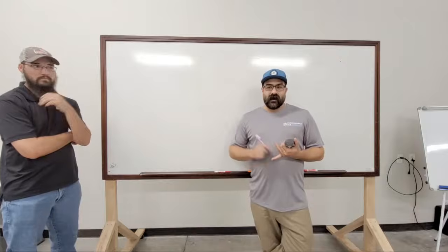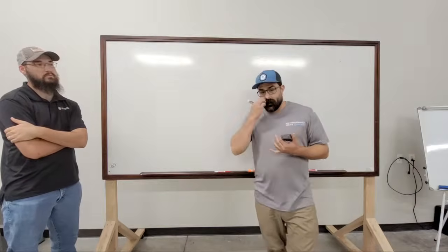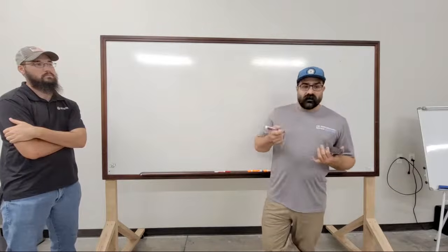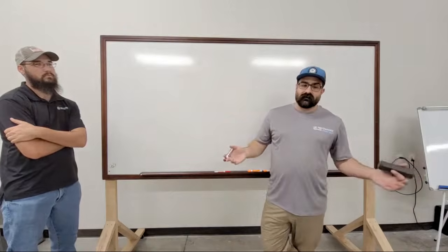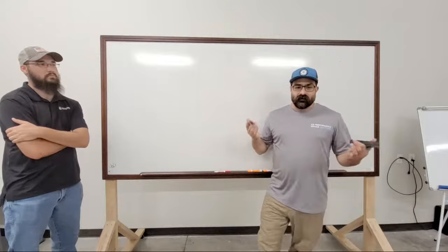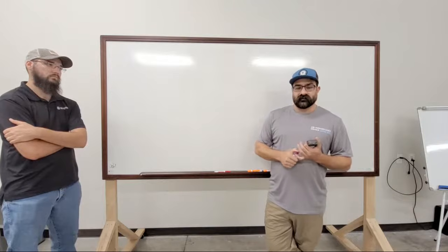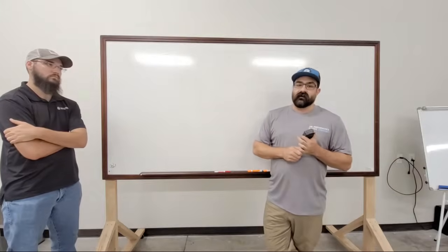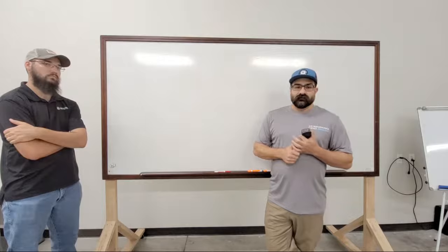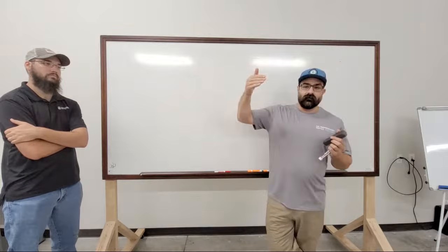I've seen systems where every box in the system is labeled VAV, regardless of whether it has a fan or not. I've also seen systems where you have no VAVs and systems where you have no fan power boxes. It really just depends. So don't just walk up to something and, because it says VAV, think it's only a VAV. It could be an old style VAV where they actually have a fan cut in further down.